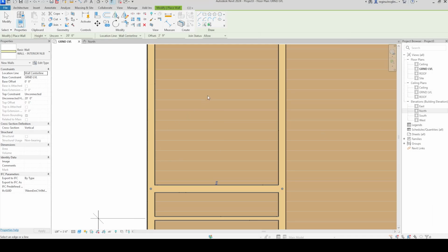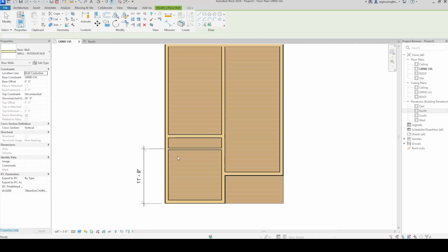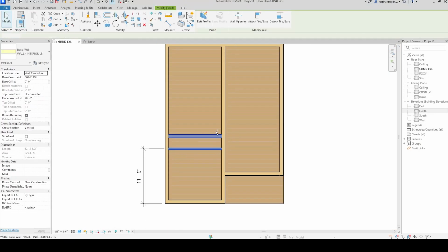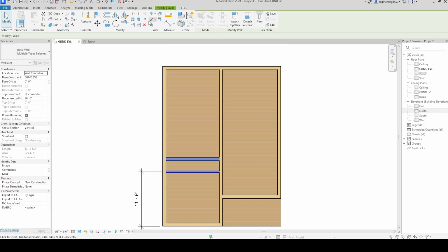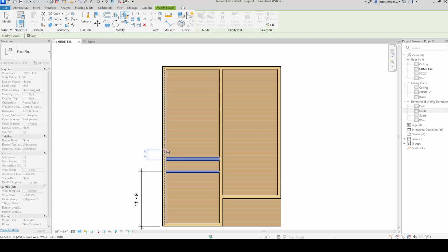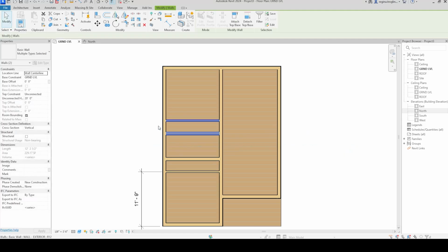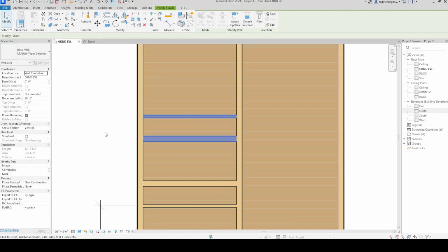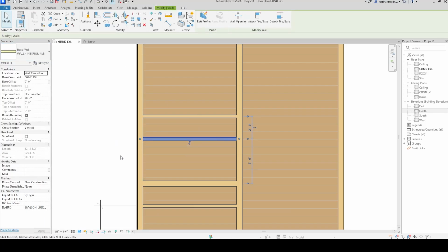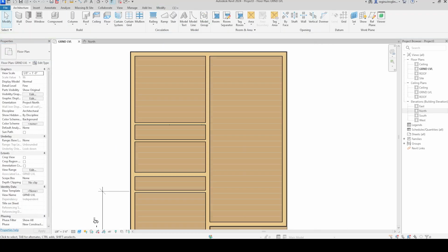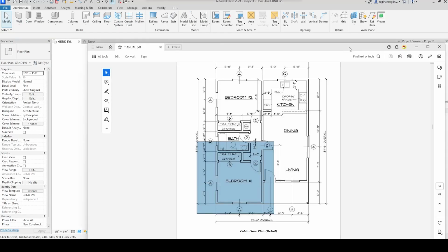So let's go ahead and do that. We'll grab both our bathroom and this wall. You're going to grab this mirror tool, draw axis mirror, and find the triangle midline that appears and drag it to one side or the other. Now we have both of our bathroom walls. Grab this one, change this to a non-load bearing wall, and then come back.